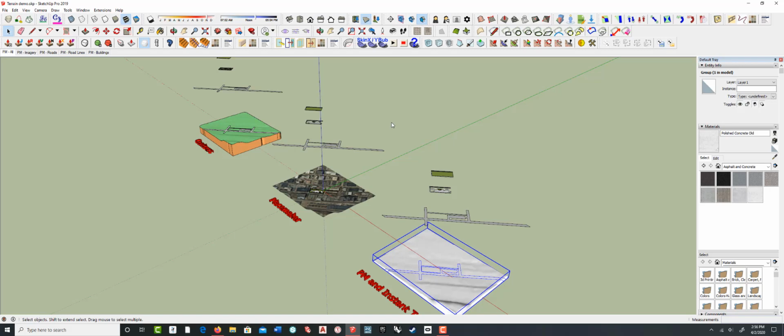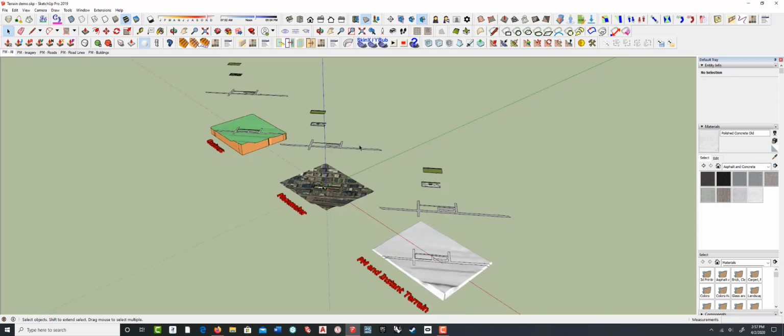Before I do anything else, I'm going to pull in an image, and I'm going to start by mapping that image on this 2D planar surface up here, because if I try to map it on here, it's not going to work very well. What I need to do is a three-step process. I map the image on the surface, then I use the texture position option, and I'm going to stretch it so that it fits perfectly on this two-dimensional surface. Line the corners up so they are all exactly where they're supposed to be. And then once I've done that, I can convert it into a projected texture, and then I can place it down onto the landform. Otherwise, it will end up being broken, a real kind of faceted image where little pieces of it are scattered all over the triangulations within the landform itself, and that's not going to help me very much.